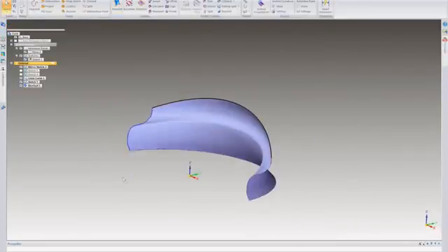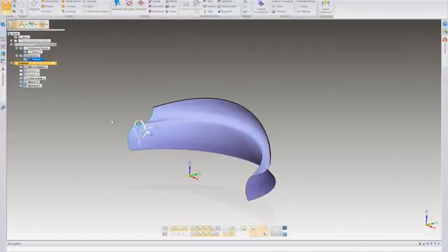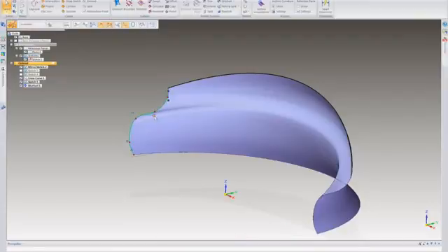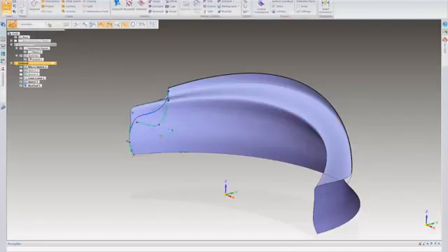All right, again, the reason I created this sketch up in the synchronous is the fact now that I can come into it and you can see I get the little steering wheel on it. Well, that allows me to either rotate it and or twist it in space, or I can actually now just grab the curve in space and start manipulating it quite easily.